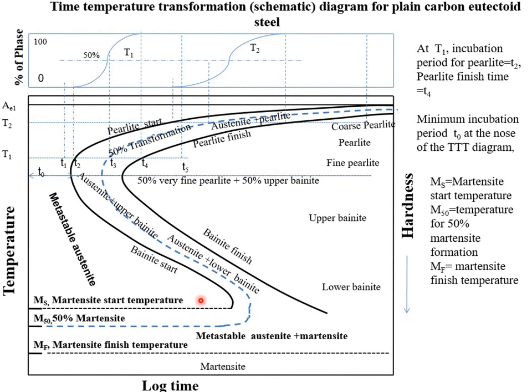Okay, so from this diagram you will completely understand the phases which should be present. So let's assume that this region is all austenite, which is a metastable state, which tends to convert itself into three phases: that is pearlite first of all, then bainite, and then martensite. It depends on the cooling rate, what cooling rate would get you what type of end product.